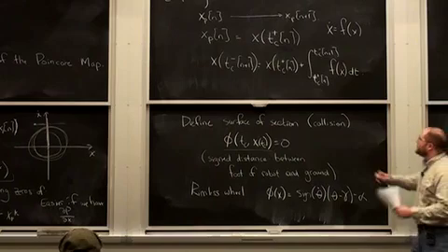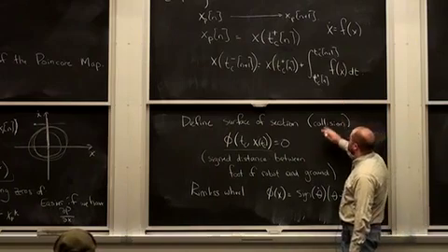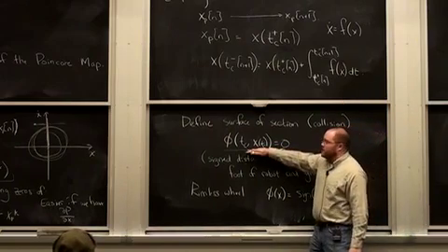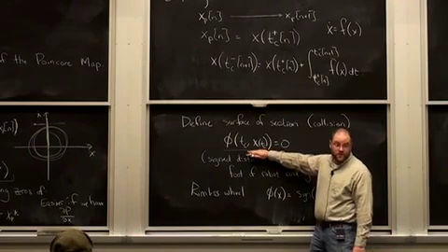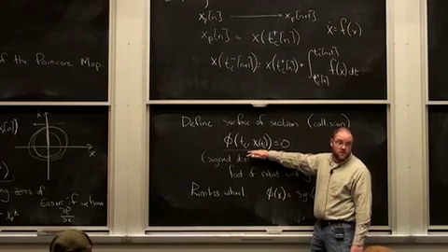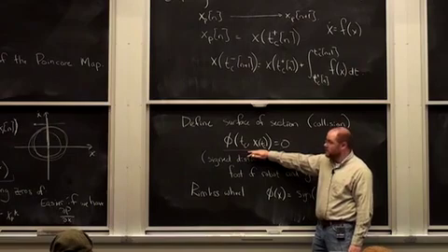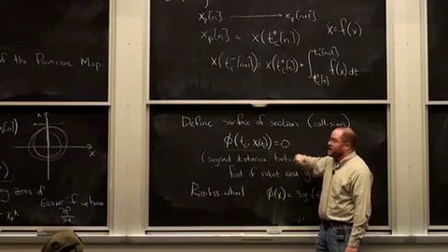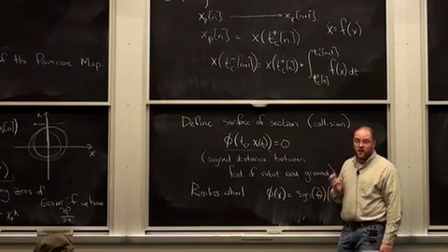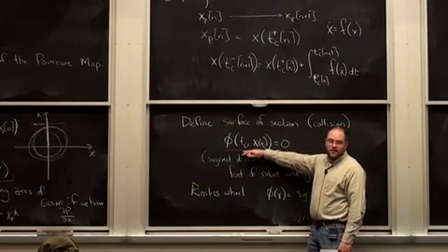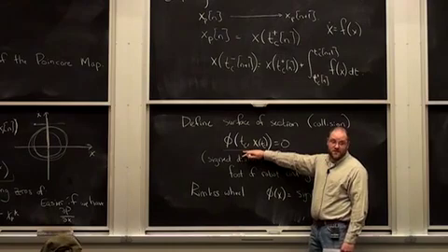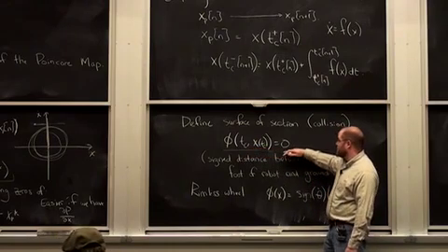Okay, we're getting closer to having this thing be well defined. In fact, this is a very common way to define a collision in any hybrid system. So systems that are continuous with discrete impacts are called hybrid systems. If you wanted to simulate a hybrid system in MATLAB with ODE, then you would very much do that by defining a function, which they call a collision function, or a collision event function, which has got zeros here.